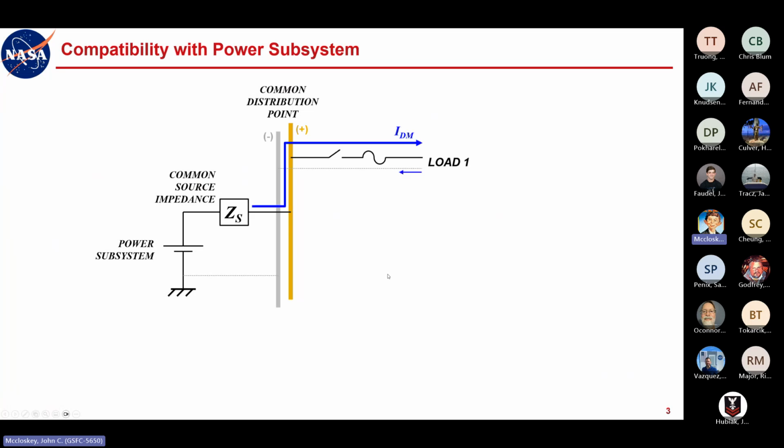So you'll have a load that will be pulling some differential mode current, and the AC ripple current on top of just the DC current draw is what the load needs to operate. But then there'll be some AC current ripple that is the noise riding on top of that DC current draw.